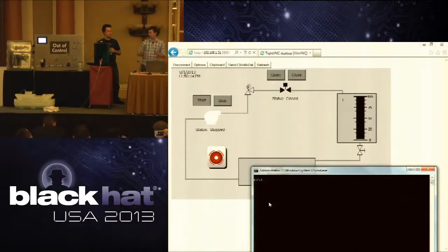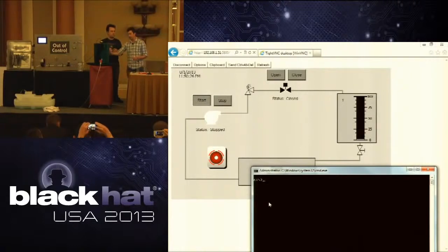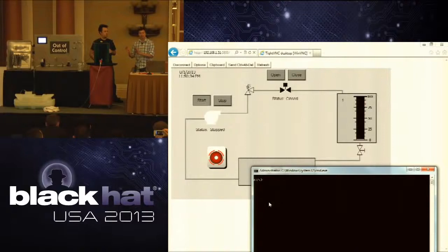So this just shows how easy it can be to force the outputs of a process. And this is not binary exploitation. This is just telling the PLC what points to turn on and off and what its worldview over the process is, and telling it to disable its own logic scanning. So all it does is what it's told to do. And the operator always makes control decisions based on what the PLC is giving it.